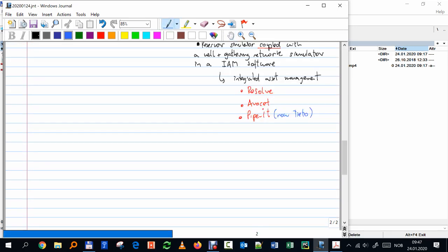Other options I can use to estimate production profiles. Material balance. But usually material balance is not enough. I have to have what I call an IPR equation, inflow performance relationship. Okay. So material balance tells me how pressure and saturations of gas, oil, and water are going to change versus time, depending on how much I'm draining from that volume. That's what material balance is.